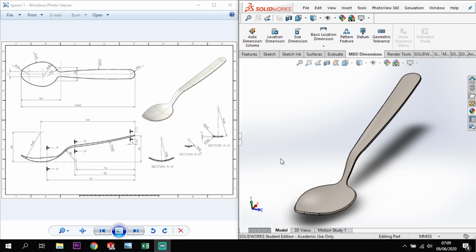Okay, so I'm going to use a range of techniques using the sketch tools to create some sort of frame which will allow me to then create this spoon shape. So I'm going to start off in terms of my sketches creating this top view here where I'll create just that profile of that spoon there. I'm then going to create a sketch in line with that, giving me a line version of these contours of the spoon, and then across these at set points where these sections intersect I'm going to put these arcs for effectively the radius of the spoon shape here.